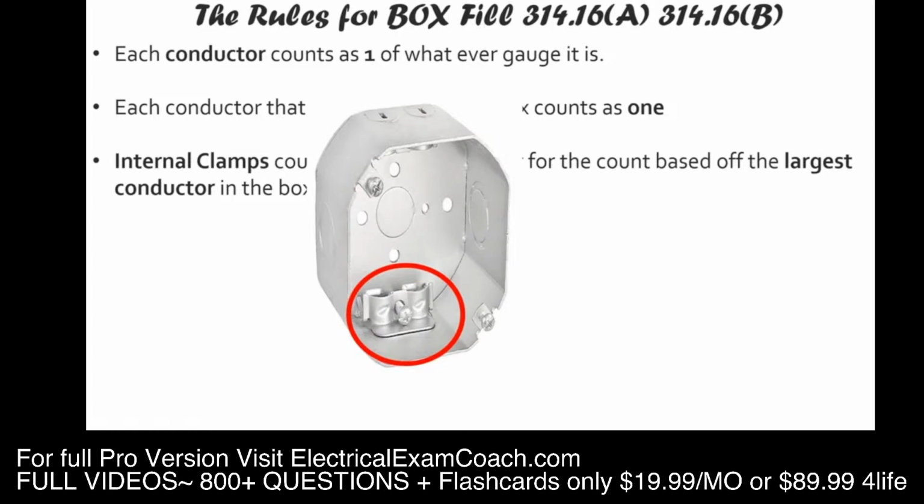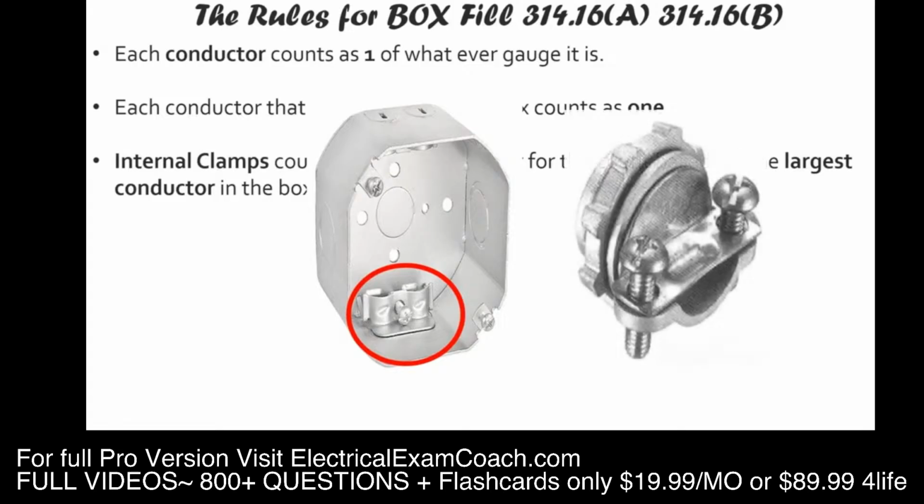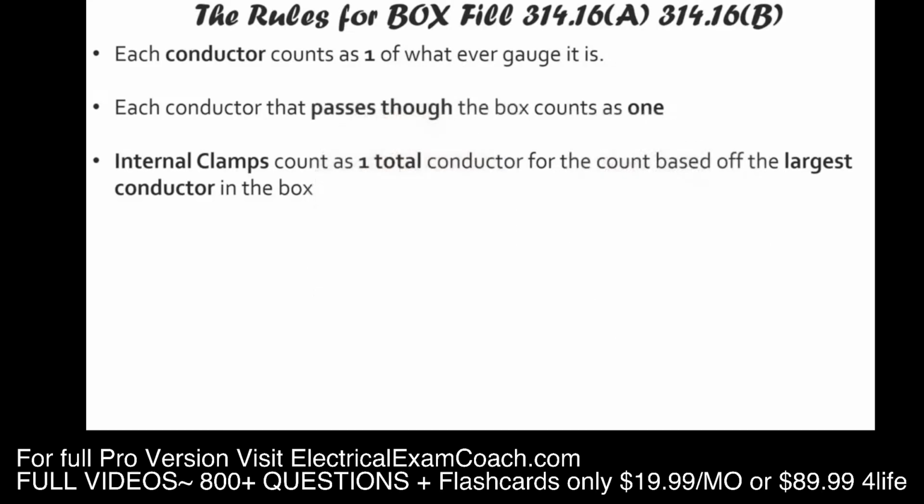All of the fittings we're going to convert over to conductors, then the conductors we're going to convert over to cubic inches, and you'll know more of what that means as we go through this lesson. This is an external clamp because the clamping mechanism is on the outside of the box, and we don't have to count those at all for box fill purposes.